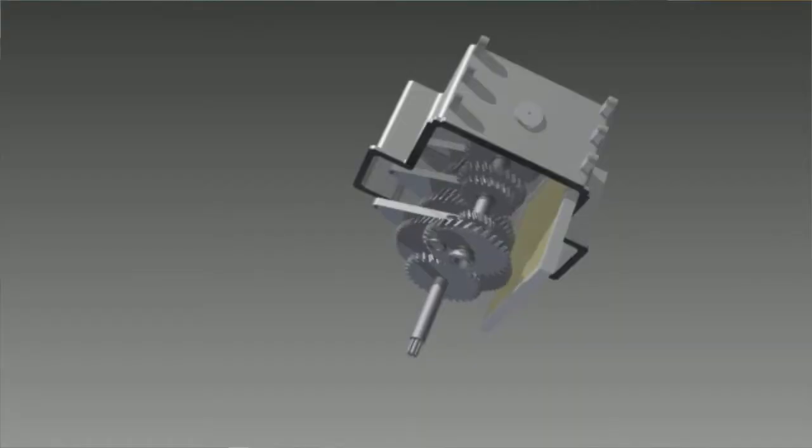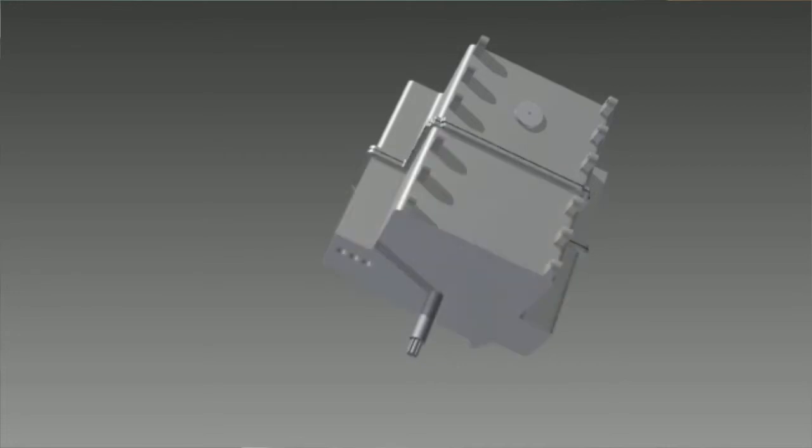The previous group did not have a functioning transmission, which is not conducive to racing, as the transmission allows the car to travel at different speeds over the same engine output. In connection with the clutch, I designed a 5-speed gearbox based off the gearbox of a 1986 Porsche 911 Carrera RS, because our car has a similar power-to-weight ratio and weight distribution characteristics as that model of the Porsche 911. On the next screen you can see the gear ratios.